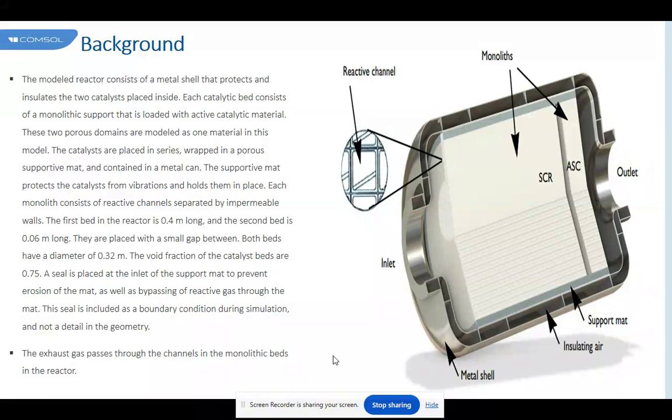When the 400 per 6.5 monolith was placed at the core, approximately 60% of the flow passed through it. On the other hand, for the opposite case, where the 400 per 6.5 was placed at the ring and covering the same 50% of the transverse area, only 36% of the flow passed through the section. Such a value is lower than the 40% expected if the curves were exactly reciprocal. This asymmetry may come from the fact that the flow approaches the substrate mainly at the center of the converter.